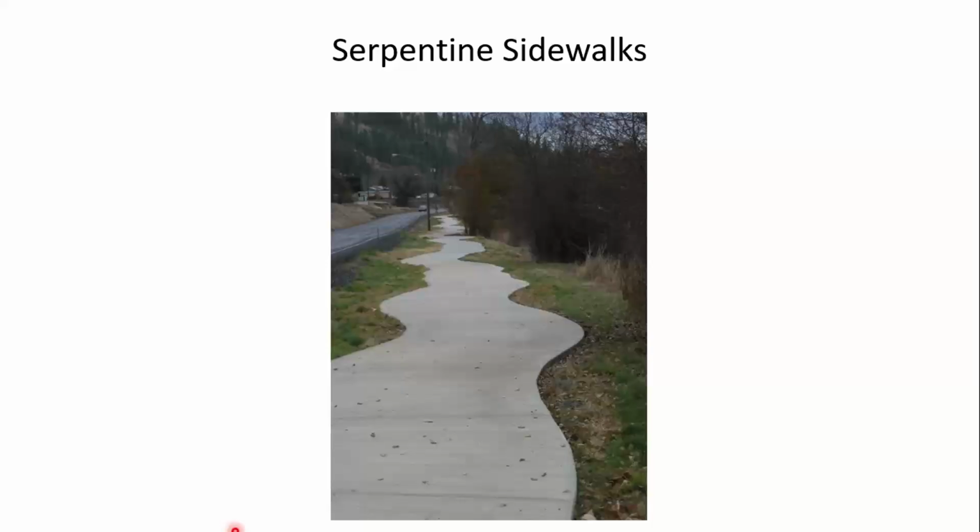I also wanted to say a few words about what I call serpentine sidewalks, and you see them from time to time around the country. I think the main reason they're used, from what I've been told, is that developers like them because they look good on Google aerial images or other aerial images if you're trying to market property or something. But if you think about it, kind of from the pedestrian standpoint and the associated considerations, I don't recommend serpentine sidewalks in the public right of way.